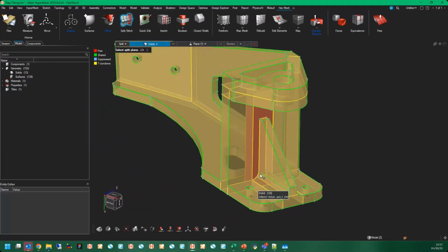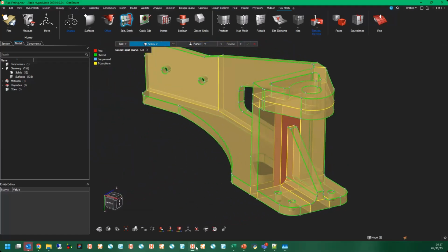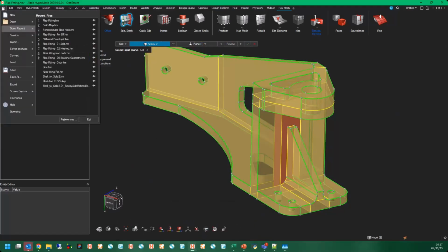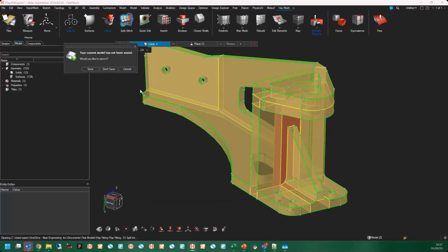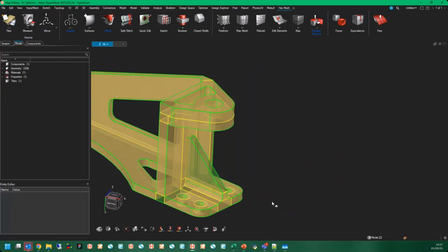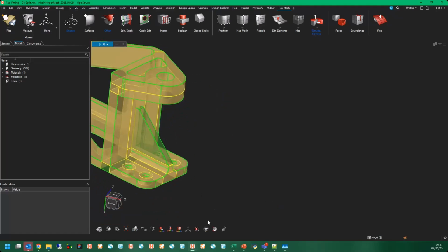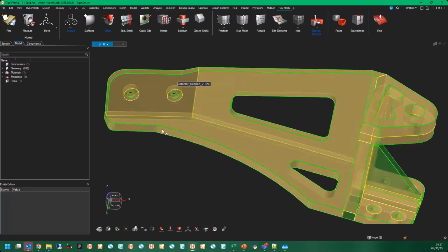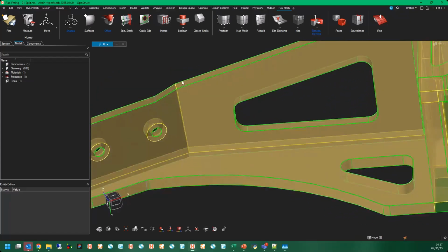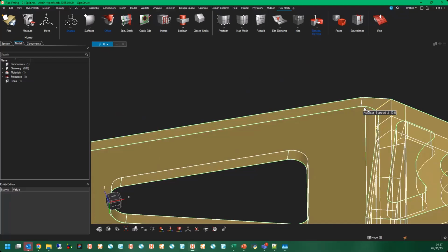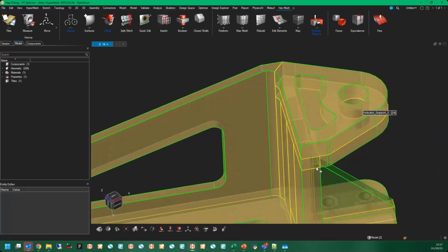I do a couple more splits here, but like I said, I'm going to jump over to the fully split one, which I don't have open, just to show you, jump into the meshing workflow. All right, so in this case, like I said, I suppressed a couple of edges that, like this one, is just too close, or creates an element too small. In this case, it was going off at a little bit of an angle. Here, it's again too close to that vertex for my liking, and so I suppressed it.